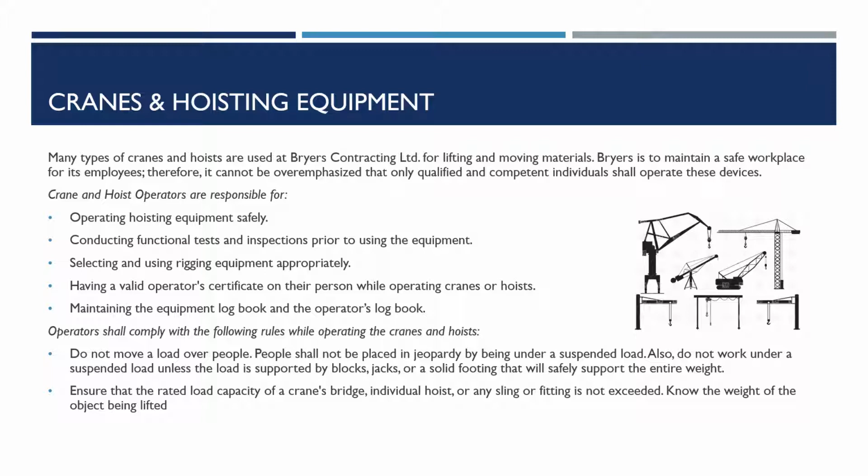Operators shall comply with the following rules while operating cranes and hoists. Do not move a load over people. People shall not be placed in jeopardy by being under a suspended load. Also, do not work under a suspended load unless the load is supported by blocks, jacks, or a solid footing that will safely support the entire weight.